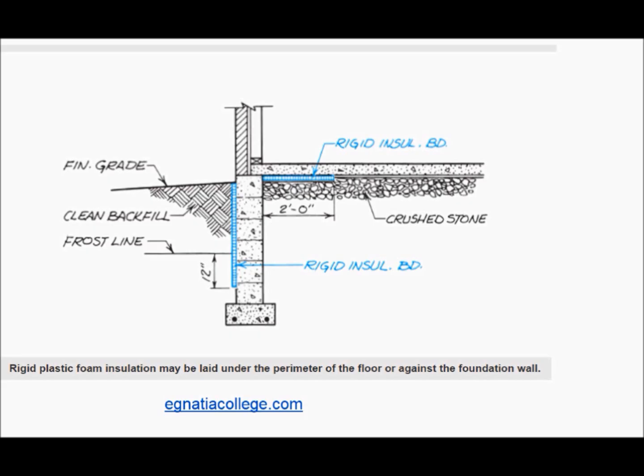Like all materials, concrete and masonry expand and contract slightly with changes in temperature. To allow for this slight expansion and contraction, the joint between the concrete slab and foundation wall should include a compressible expansion joint material. Expansion joints can be made from any compressible material such as neoprene or composition sheeting material. This expansion joint filler is as wide as the slab is thick and is simply placed against the foundation wall before the concrete is placed. Concrete slabs.